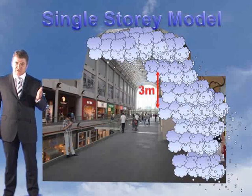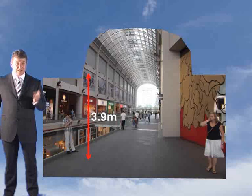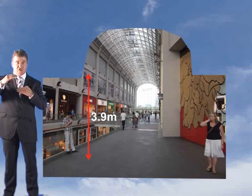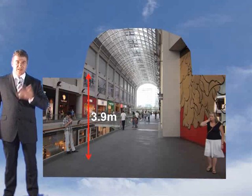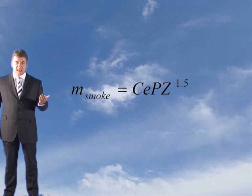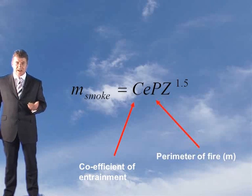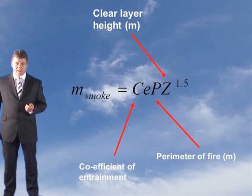To be valid, the smoke cannot rise more than 3 metres before reaching the base of the smoke layer. Now, in this case, we've already established that the clear layer height is going to be 0.5 metres from the spillage at the highest point. So, in other words, this formula is valid. You can use it. And this is a formula you should have used. M smoke equals CE times P times Z to the 1.5, where CE is your coefficient of entrainment, your P was your perimeter of your fire, and Z is the clear layer height.